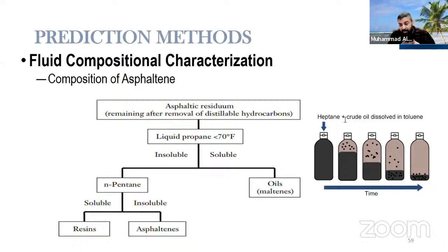So it doesn't matter. I have worked on both light oils as well as heavy oil, and both have the tendency. It doesn't matter how much asphaltene it has. Sometimes, for example, the light oil might have 7-8% and the heavy oil probably has 5-8% or maybe 8%. So it doesn't matter how much weight percent it is. When it wants to precipitate, it precipitates.